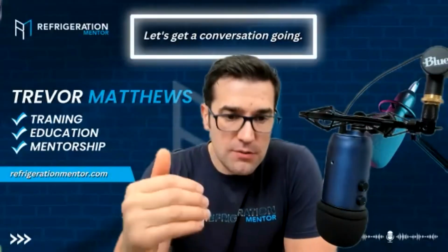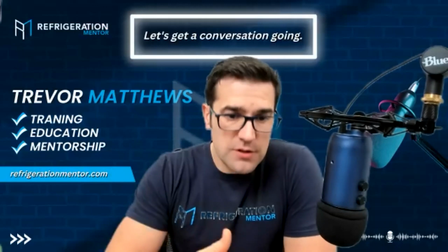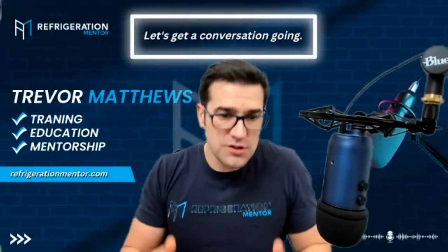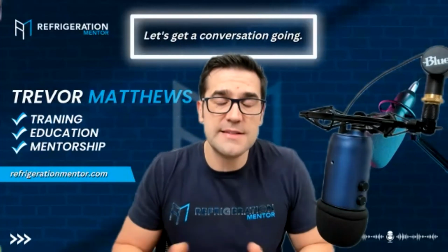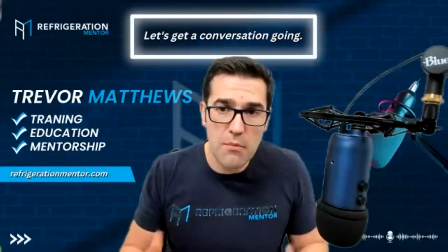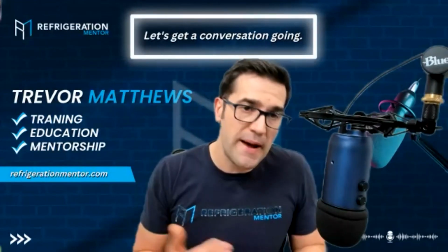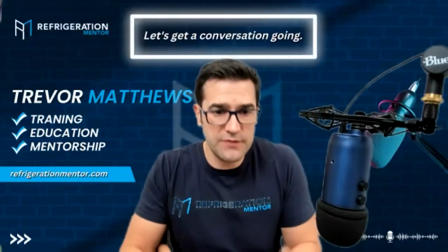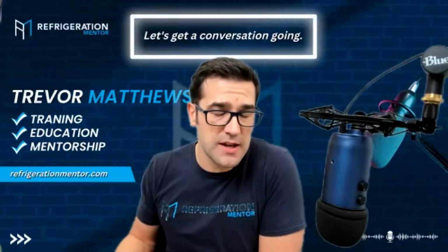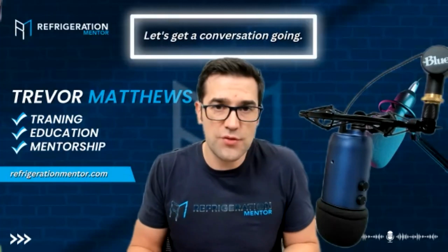Yeah, and that's the big thing. You need to log this stuff. You got to have a journal. You got to have a book. Those technicians that do, they're growing. I'm telling you, I've done it and I've seen it. You'll understand that site, that compressor, a lot more when you have that information because you can go back to it. Oh, here, this is what the resistance was, and if the resistance starts to change over time, then you start to see a trend happening.